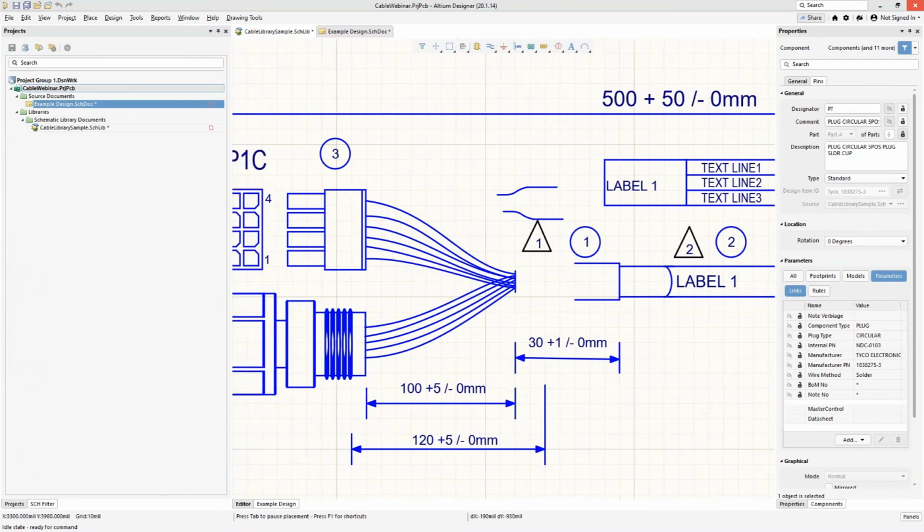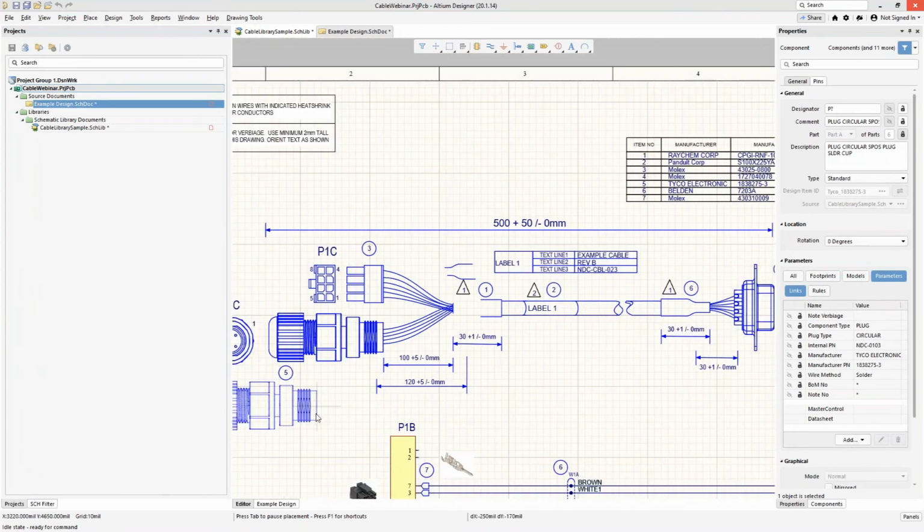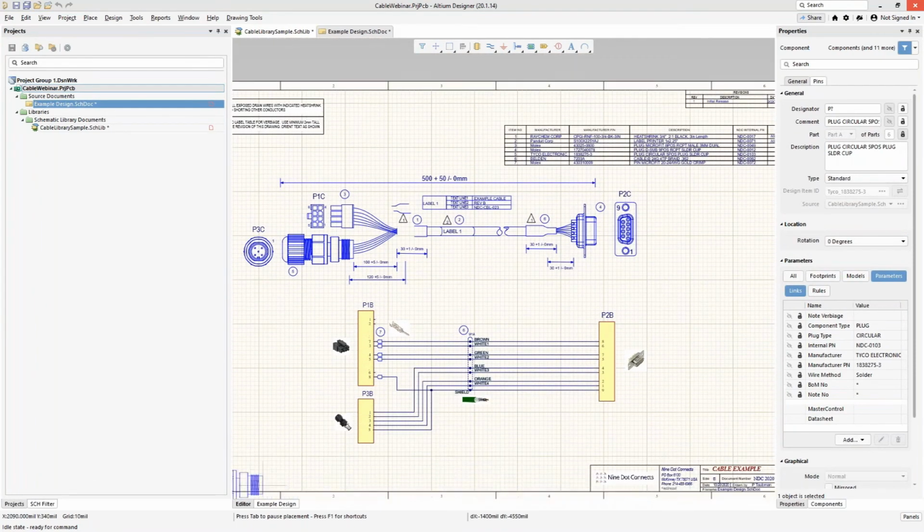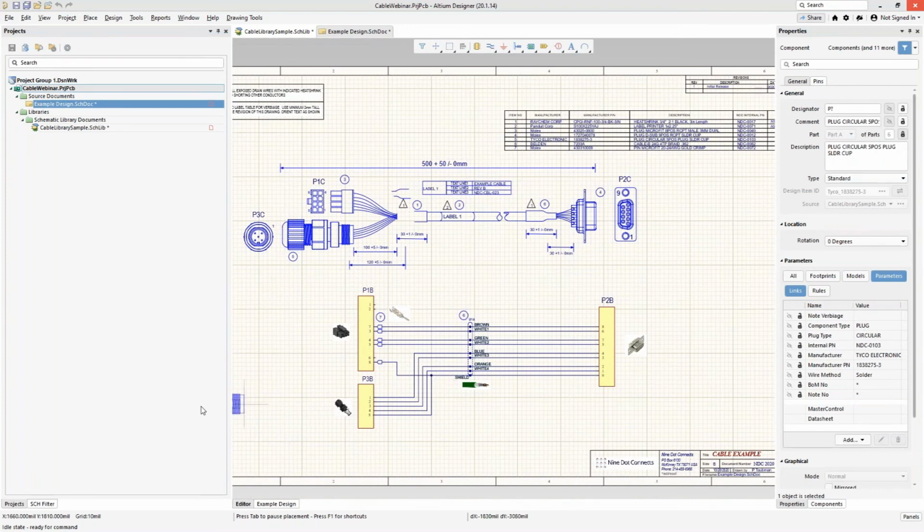The other thing that you're going to want to do too, let me zoom this out so I can get down here in the corner, is pile them all together in one area. And there's a reason for this. So I'm going to place this one. Before I do this, I'm also going to hit the Tab key, because if you're familiar with multi-module components, they're going to become independent of each other. So either I fix everything now, or I'm going to have to fix them individually. And once you scatter them, it becomes really hard to find them. So I'm going to place this down here, and I'm going to just keep dropping them until I round about to the next part A.